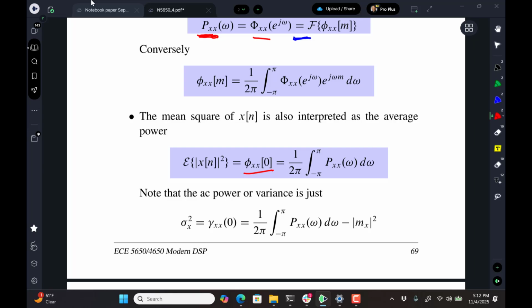And that's what you measure with a spectrum analyzer. And most spectrum analyzers give you the ability to integrate the power spectrum on the display, so you can make a power measurement right on the spot.